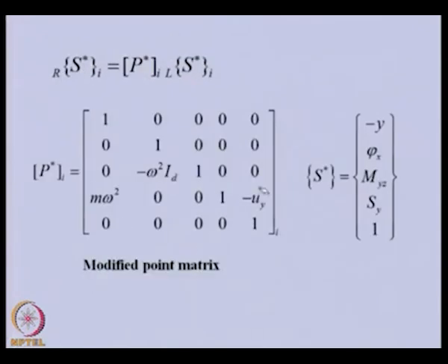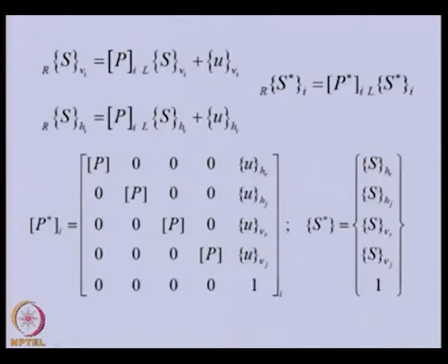Now, on the same lines as we did for the field matrix, if you want to analyze both plane motion, and also damping or gyroscopic effect, we need to have both plane state vectors and their real part and imaginary part components. So again I am expanding that here. You can see the point matrices here.